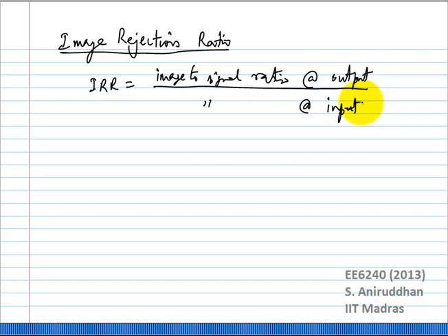And again, for a receiver, you can decide it with respect to the amplitude and phase mismatch between the two paths. I'll leave that up to you; you can go ahead and read the textbook for that. Razavi has a pretty good explanation of the image rejection ratio, so you can take a look at that. But the primary thing to remember is that it depends on both the amplitude and the phase, okay, between the two paths.